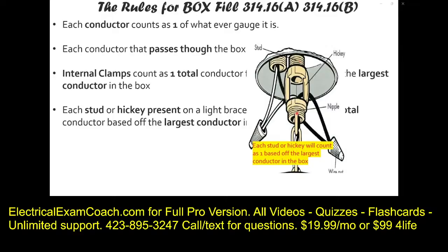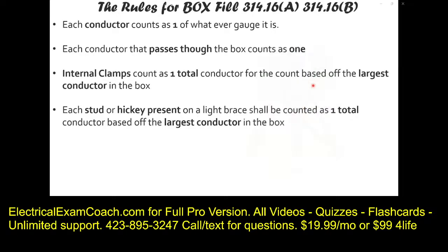Or, this would be a nipple, but they're calling this the stud and this a hickey. And they still use this terminology on exams today, so you definitely need to understand. In this scenario here, in this picture, the stud would count as one of whatever gauge was in the box that was the largest, and the hickey would count as one of whatever gauge was in the box that is the largest. And we're going to do lots of practice, so don't worry about it.